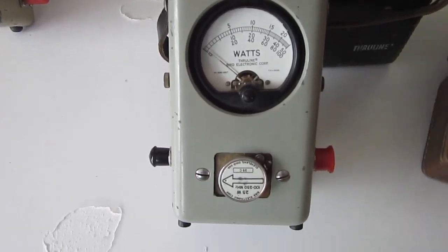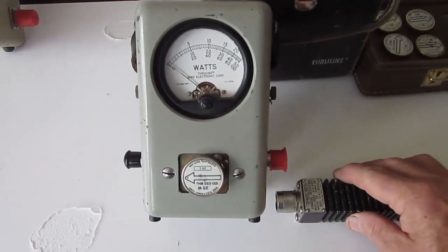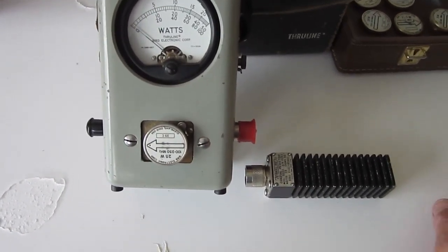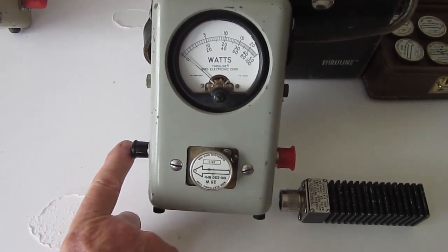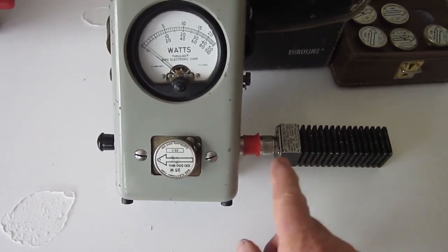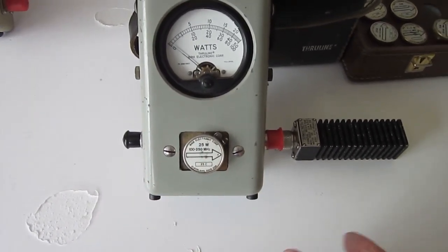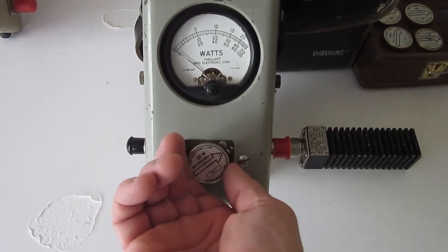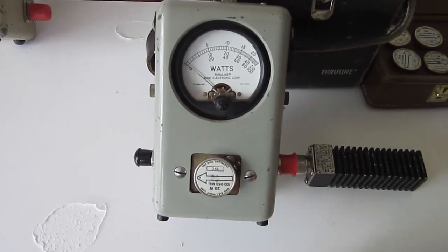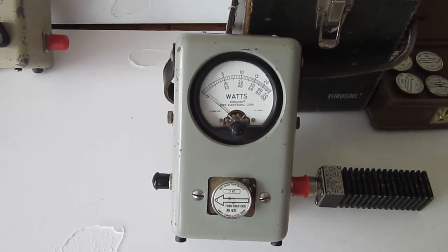Now in addition to a range of modules, I also purchased a 50 ohm load. Now a 50 ohm load's quite important because you can hook your transmitter to this side of the meter, put your 50 ohm load onto that side of the meter, and ensure that you have full forward power, 25 watts in that direction, and because it's a 50 ohm load, you should have little to no power in the reverse direction. And by doing that, you can actually prove your coax cable setup.